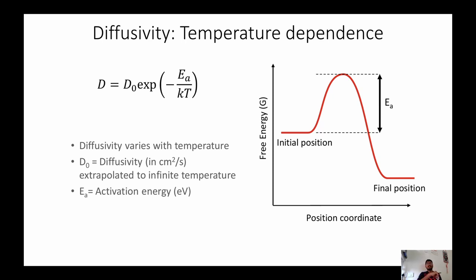So now let us say, there are two ways to improve the diffusion. One is the diffusivity, one is the time. So how to increase the concentration of the dopant inside the crystal? Okay, and that depends on the square root of Dt.